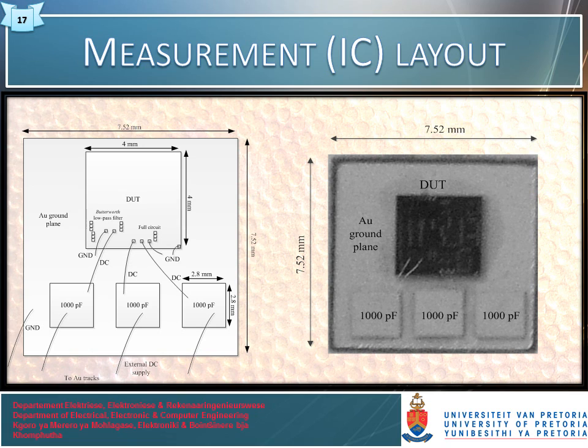The setup to accommodate the measurements of the prototyped IC is shown. In order to ensure good common ground and minimum interference from surrounding components, a ceramic substrate was gold sputtered, serving as the ground plane, and epoxied onto the surface. The device under test, or DUT, was wire bonded for the required DC and DC ground connections, through a 1000 picofarad decoupling capacitor and onto an external in-house designed PCB, shown in the next slide. The substrate was sputtered at an infrared detector facility, where it was also epoxied and bonded.